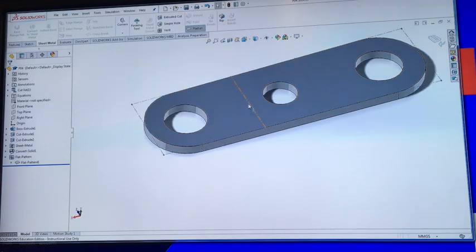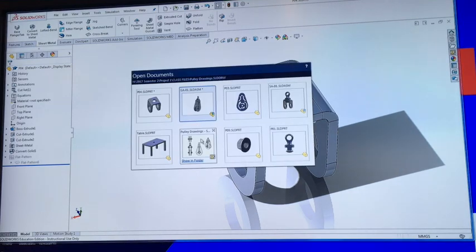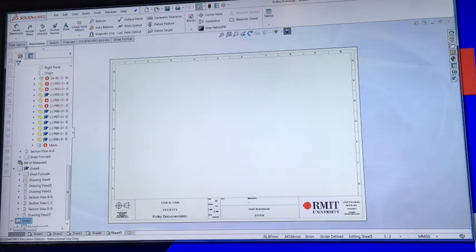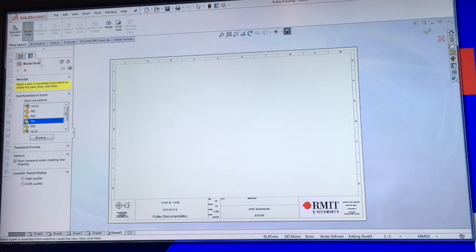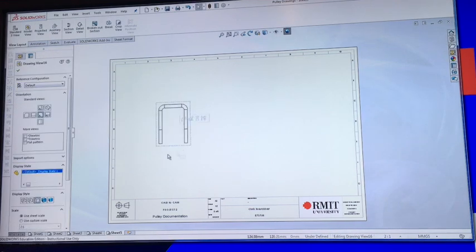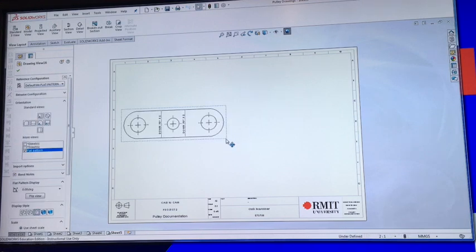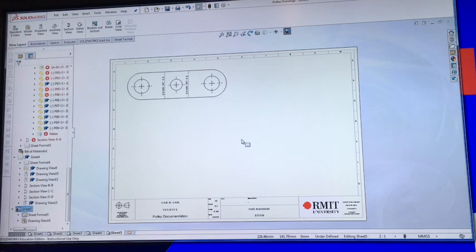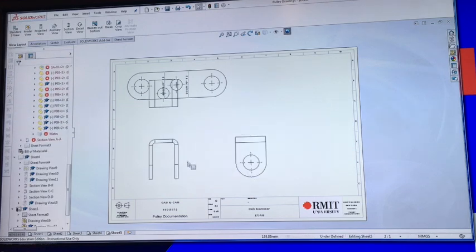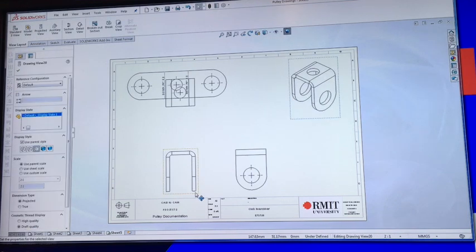Okay, now that includes bend lines here as well. So in your drawings on your page for this part, what you're now able to do is add a model view of part 04, and you can select that model view and select flat pattern as an option. Okay, and that's how you can create this flat pattern view of that part. On that page you should still have your standard 3 view parts and an isometric. But you'll also add in that flat pattern.